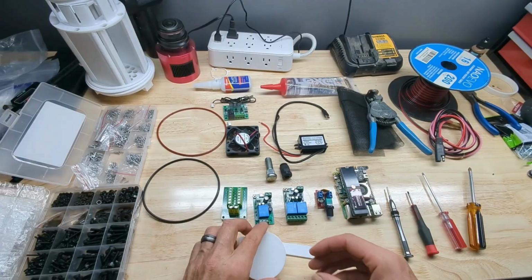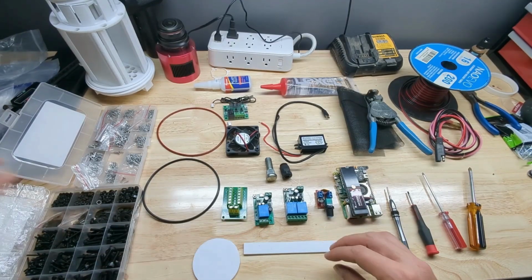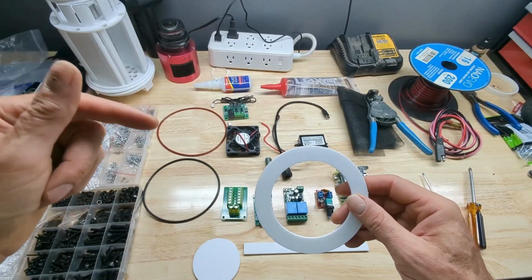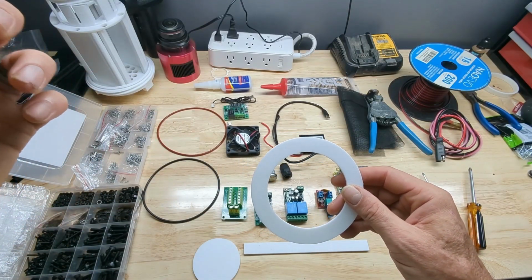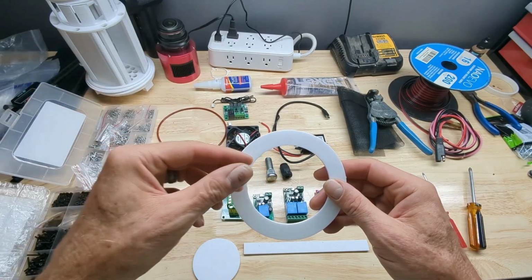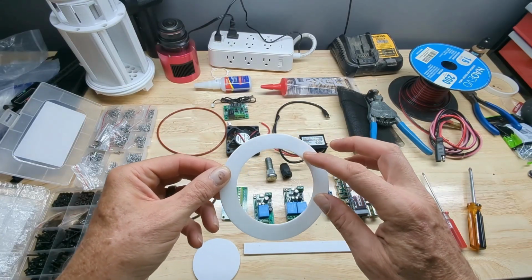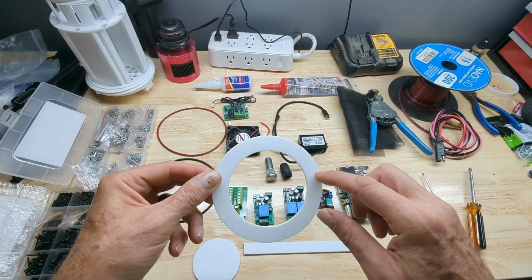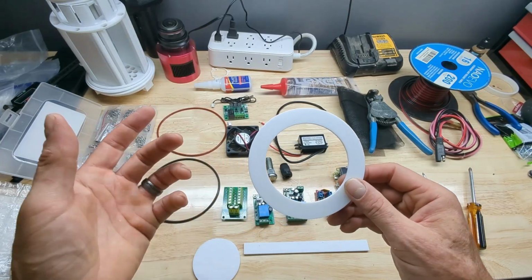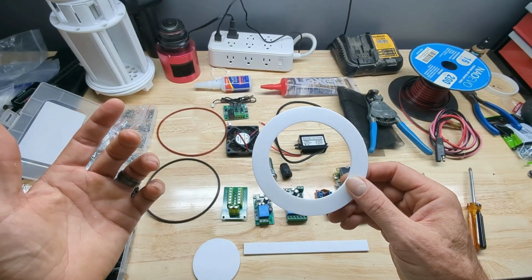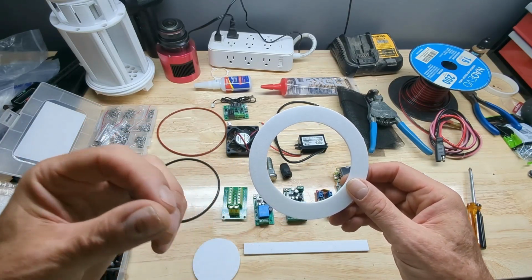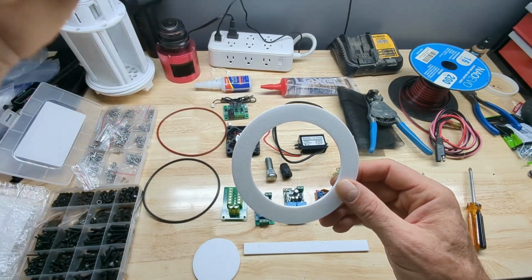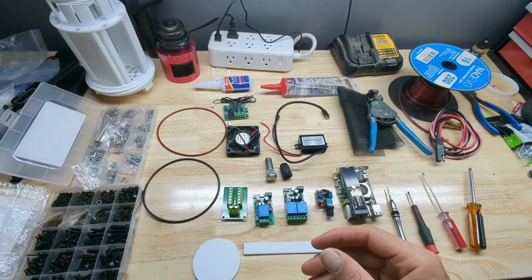And there's also a stencil for if you're printing the standard tube. The vents on it have the same vent ports on the neck of it that the tall enclosure has, but on the bottom, the ports are actually around the edges like this. And on that system, it's really designed for kind of a chimney effect where it's a passive heat transfer. So as it warms up inside, air will pull through it and move itself up to the top. Hopefully that makes sense.